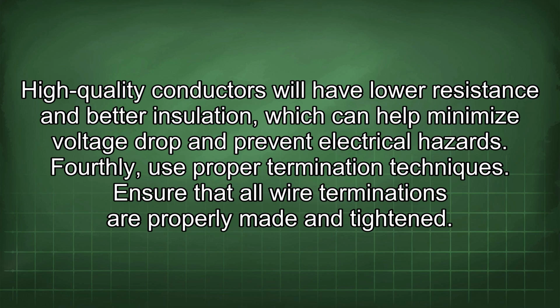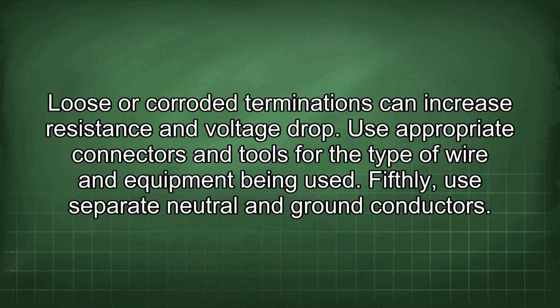Fourthly, use proper termination techniques. Ensure that all wire terminations are properly made and tightened. Loose or corroded terminations can increase resistance and voltage drop. Use appropriate connectors and tools for the type of wire and equipment being used.